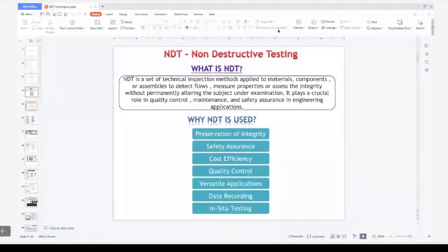In addition, since it's a layer by layer process, defects form at the interface between two layers. And you use an inert gas. Any failure in the inert gas leads to oxidation, contamination, inclusions. So these problems you typically encounter in additive manufacturing. So just putting it up here.